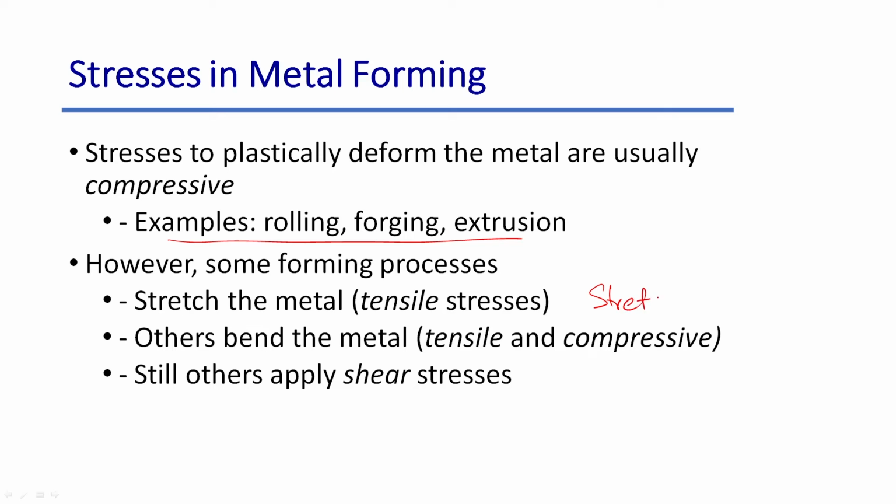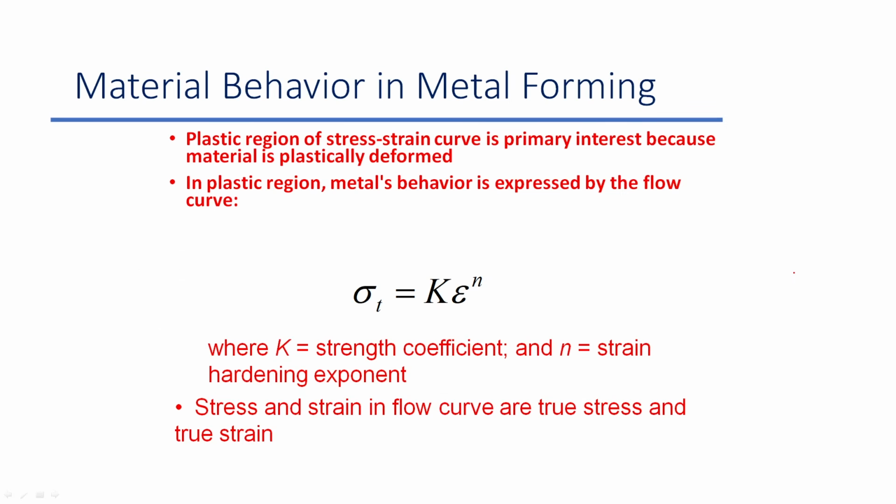Stretch forming uses only tensile force. Then you can have bending forces which can generate tensile and compressive components, and each of these processes can generate shear stresses. That is very clear. But you also need to know about the material behavior per se. I gave you some fundamental equations. One of these is this: true stress is equal to K epsilon to the power n, right? That is very fundamental, as you understand.